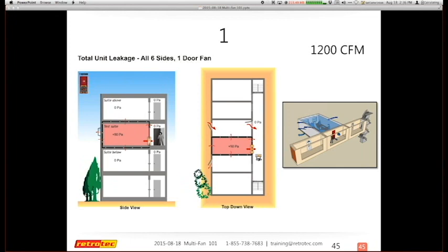So now we have some better illustrations to go through that. We're going to go back to measuring our unit. Looks like it's A, B, C. We'll measure unit C. And we have illustrations to show it in plan view, elevation view, and a three-dimensional view. So again, the goal here is to start with pressurizing one unit. I must open some type of pressure relief on the two side units next to that. Right now my stairwell is open all the way down to outside, so I'm able to get equal pressure throughout as though I'm outside in general. So both stairwells are wide open.